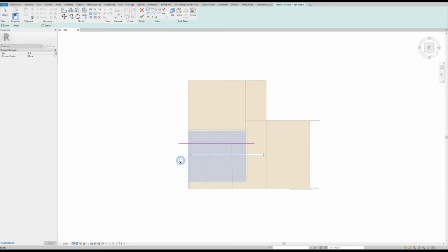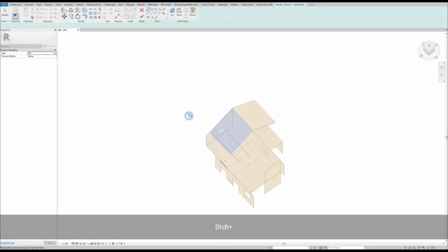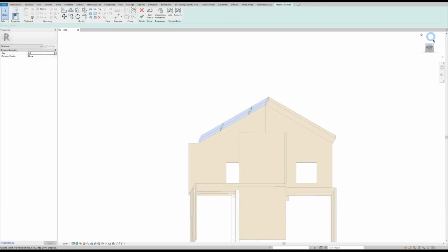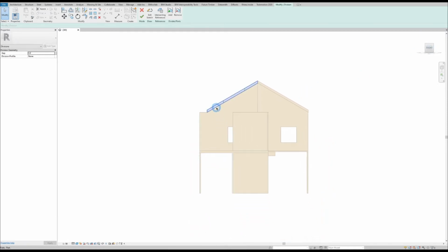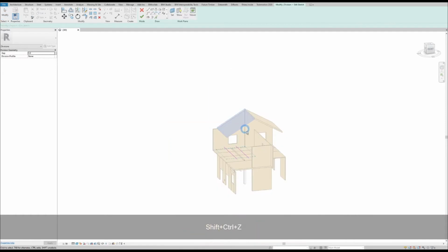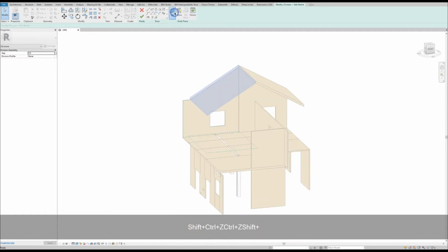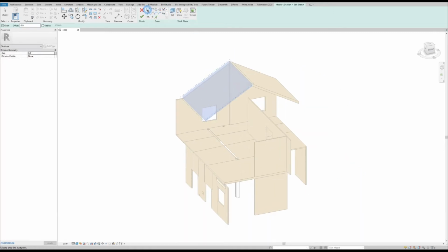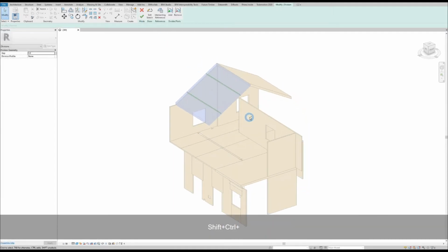So for example, if I'm cutting here and here, we can see that the cut line has actually gone plumb or vertical. You wouldn't typically cut it like that. You would actually want it to be perpendicular. The solution is to set the correct plane, and then you'd be able to cut perpendicular on that plane, as we can see there. So those are quite important things to understand.